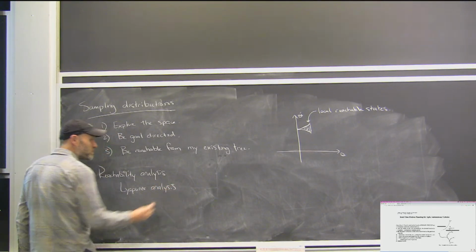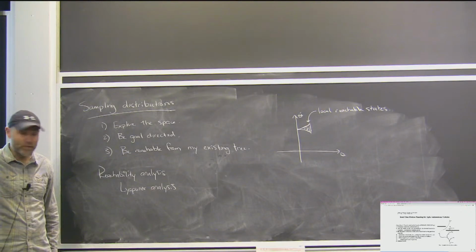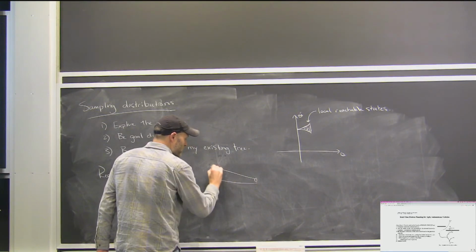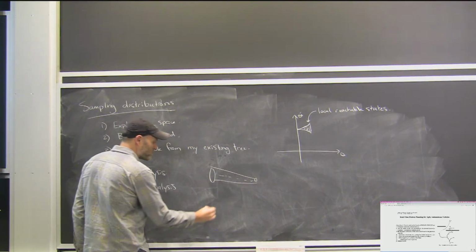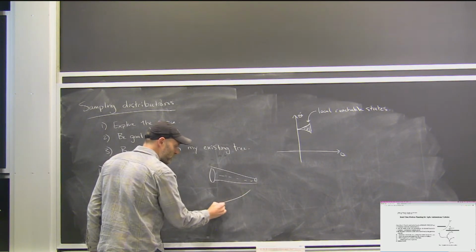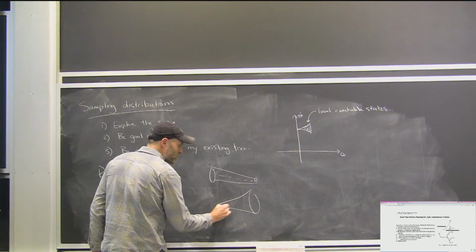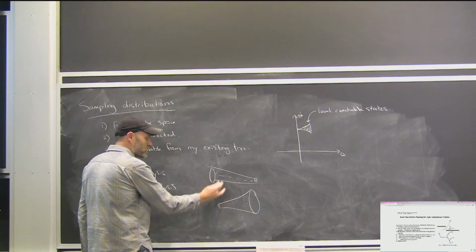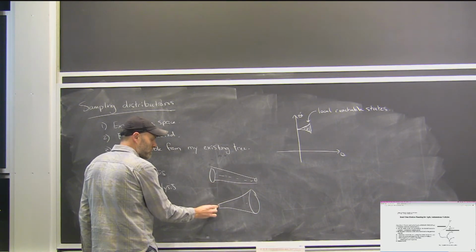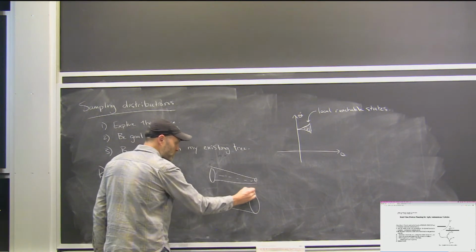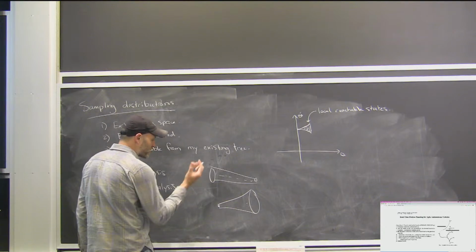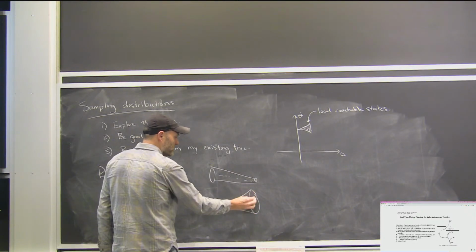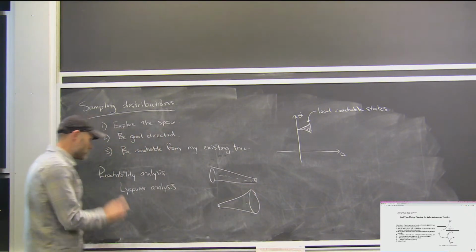The one time we talked about it a bit was when we talked about the funnels, remember? When we talked about the time-varying Lyapunov functions that were going backwards in time, the exact same definition of funnels could give me a forward reachable set from some small set of initial conditions. I can talk about growing myself to the biggest possible region. All that changes in this computation is changing the constraint: I'm going to start from an initial point and maximize the set of possible states, but I can still search for a Lyapunov function such that I can always go downhill. All the same math works to talk about reachability analysis.